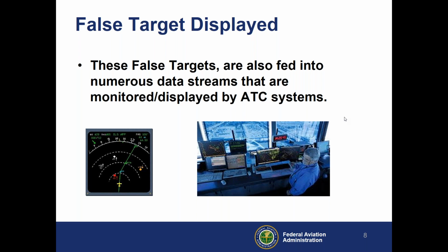and it's going to get to be worse because right now we are painting our picture of ADSB traffic by local ground-based monitoring stations. In the future, we're going to go space-based. And I can guarantee you that if you've got a repair station tucked into a little valley that's not being seen by the ADSB ground station, once we go to satellite-based ADSB, you're going to be seen.